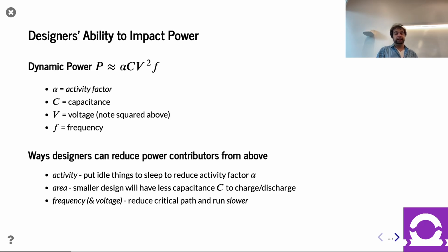Voltage is the one that's actually really important. Quite simply, if you crank the voltage up on your circuit, it goes faster. You crank it down, it goes slower. But there's a nonlinear impact on the power, right? Because of that, if you can make your circuit shorter in terms of delay, with fewer FO4s from the last lecture, you can turn down the voltage. And because you turn down voltage and get a quadratic reduction, you can really save some energy.